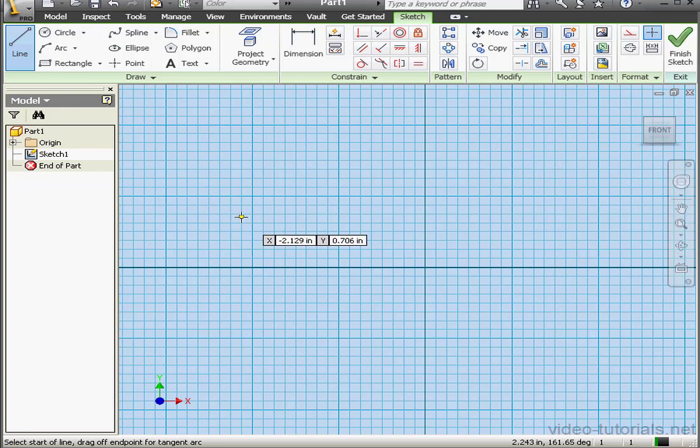Press the Tab key to change the focus to the X coordinate input box. Let's enter -1. Tab over to the Y input box, 1, and enter to accept. And we've created our first point. Now we're ready to enter our second point. Let's enter values of 1 inch and tab, 0.5, tab.